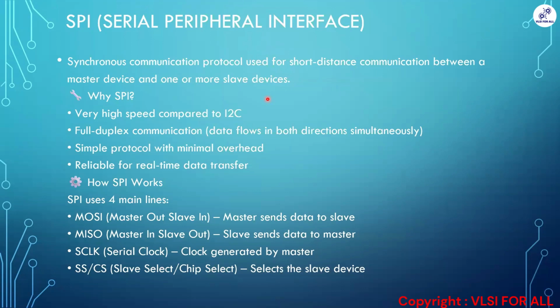And it's very high speed compared to the I2C. It is a full duplex communication because we'll be having MOSI and MISO lines, right? So data flow can be from both directions simultaneously. And it's a simple protocol with minimal overhead. And it's a more reliable data transfer.